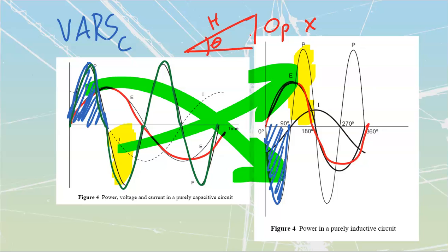Now, if I've got a completely leading circuit, a purely capacitive circuit, then I'm going to have a value of 1, because the sine of 90 is equal to 1. Punch it in your calculator. Take a look if you don't believe me. It's going to come out as a value of 1, so if all I have in the circuit is capacitive, all of my power is going to be reactive power. We'll see a bunch of that in the next learning task, which is going to be calculations once again. All right, let's go over to that one next.